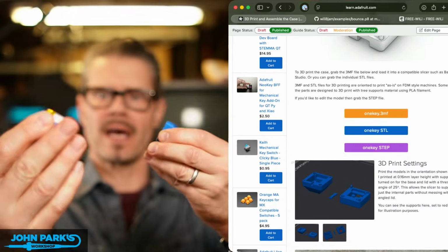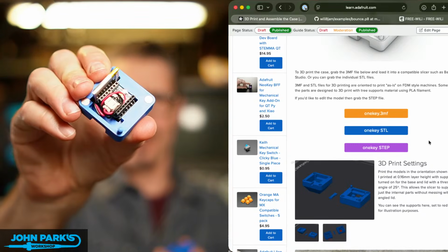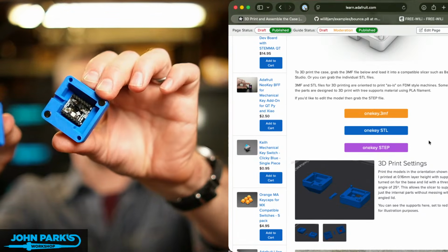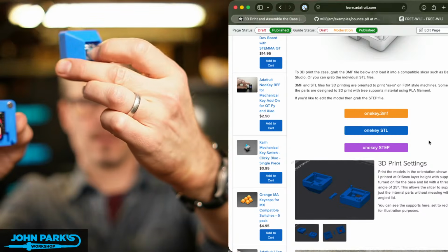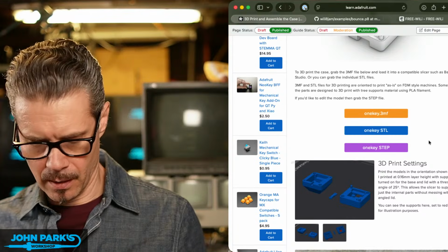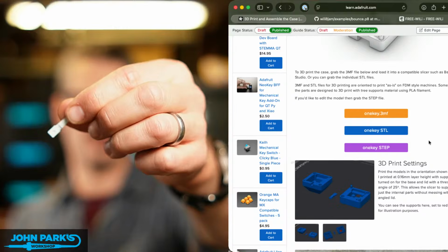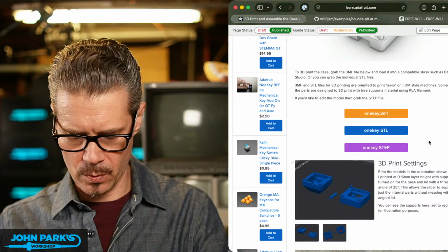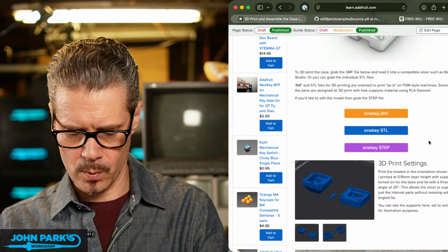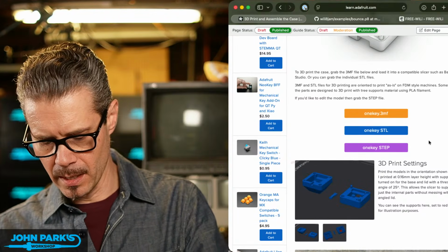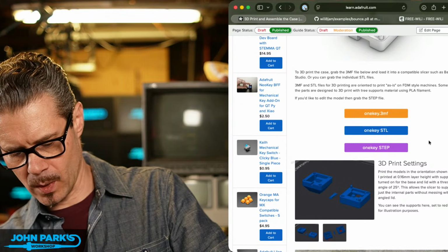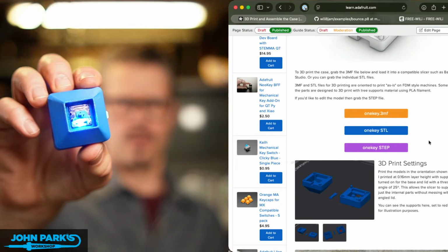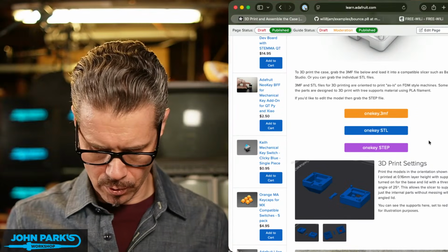So if I open that up, you can see I've got a pretty exact fit for this stuff, and the NeoKey mechanical key switch snaps in there. Also, I've got a little toggle there to extend the on-off switch, so we didn't have to add a separate on-off switch. All of that stuff wants to be fairly precise, so that's why I included a 0.16 value there on the 3D print.